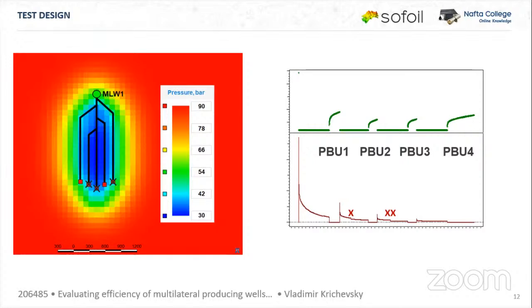And the first flow that we see in a horizontal well is the early radial flow, which is like a radial flow around the borehole. And the time of this flow actually is from approximately 10 to 100 hours. That was our estimate from the previous study that we had. So we do not need to do very long pressure buildups in order to see this flow. And this flow actually depends on horizontal permeability, vertical permeability, and the effective length of the well.